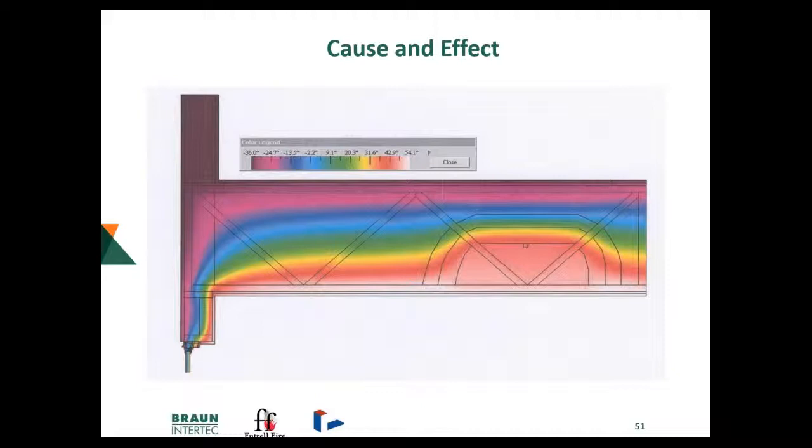I have two slides here that are very similar to slides Gary and Steve put up, but this is showing tenting of a sprinkler system in a combustible concealed space, and it's the thermal lines or modeling of what the temperatures are in that space. And I only show this because this is something that needs to be done if you're going to try to conceal water-filled sprinkler piping in these spaces. So if an option is to blow it full of insulation, you're going to have to make sure that the warm air is going to keep that water-filled piping from freezing.